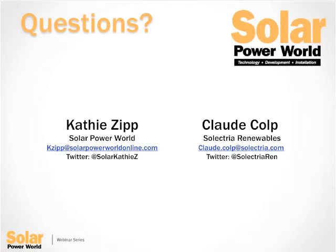Someone else is wondering, since an arc occurs in only milliseconds of time, how can a shutdown in 10 seconds be considered as rapid? I think that's a relevant question. So the rapid shutdown requirement was written in such a way to not eliminate the opportunity to reduce the voltage below what most consider lethal voltage. When you start to get to 50 volts, things start to really hurt. But 30 volts is deemed manageable from an encounter perspective.